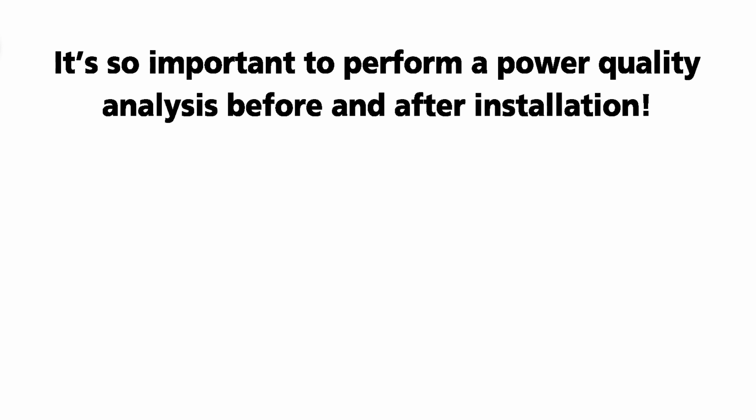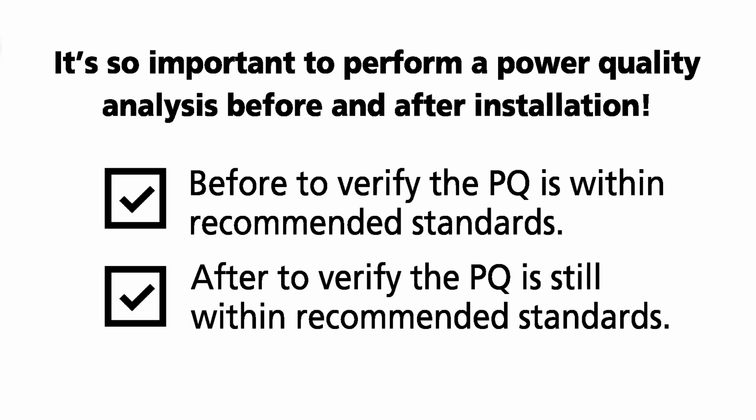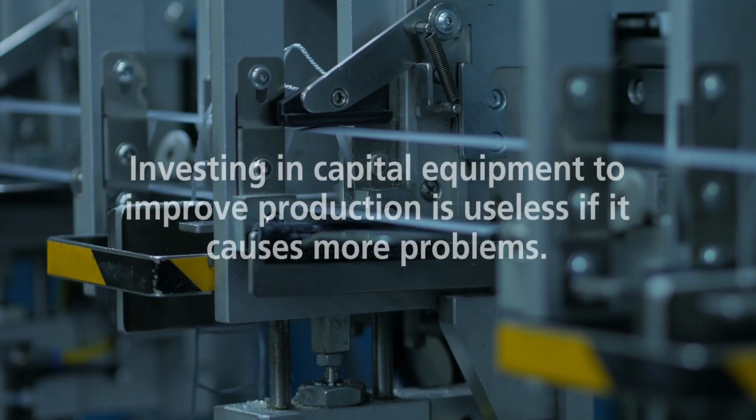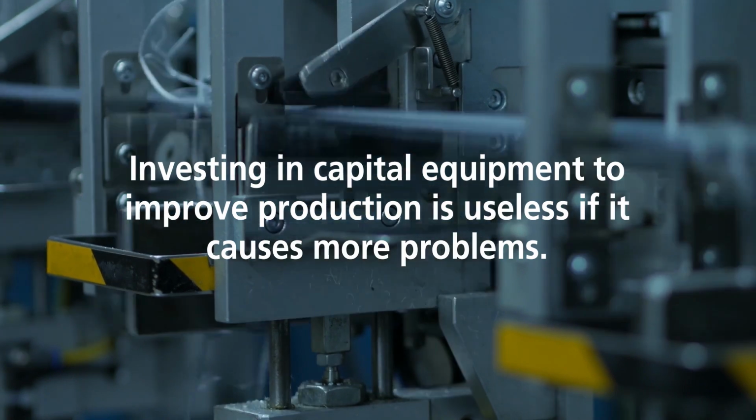This is why it's imperative to perform a power quality analysis before and after a new piece of equipment is installed. Perform the test before installing the equipment to verify power quality is within the recommended standards. Perform the test after installation of the equipment to verify the power quality is still within recommended standards. Investing in capital equipment to improve production is useless if it causes more problems.